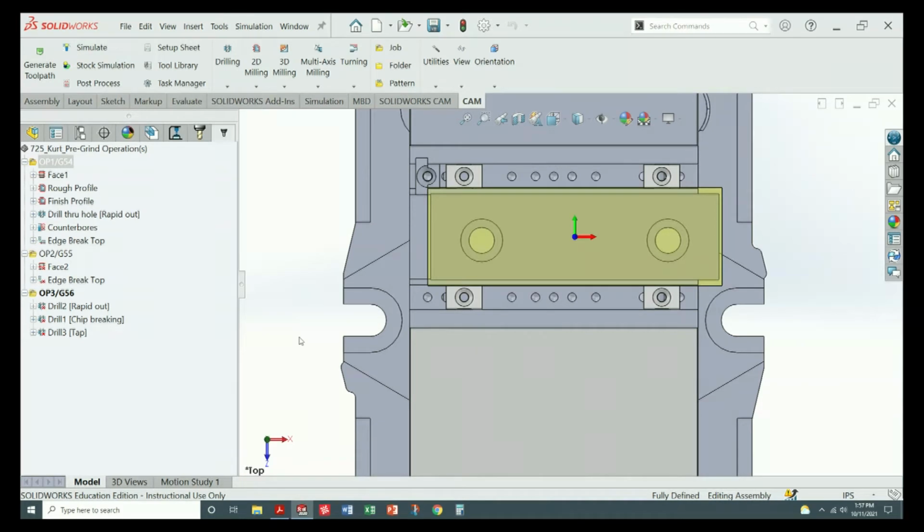So in our Intercon software, it's asking for the start position in X. Now this question says, where do you want your cutter to start facing? In X only, in relationship to G54. And I need to give it a number. So, I'm going to lob a softball at you. My stock is 6.125 inches long. Half of that is 3.0625.